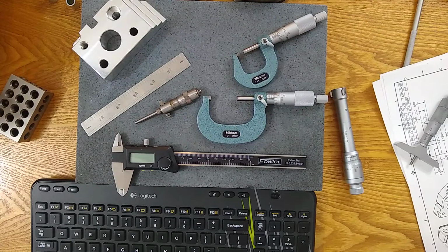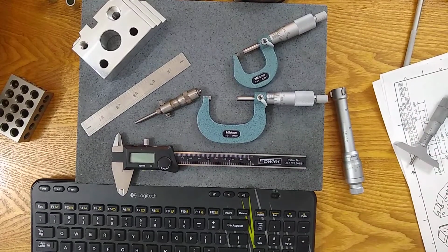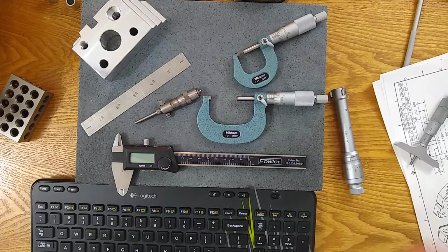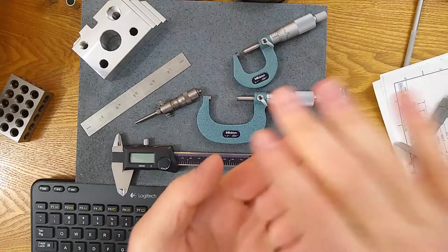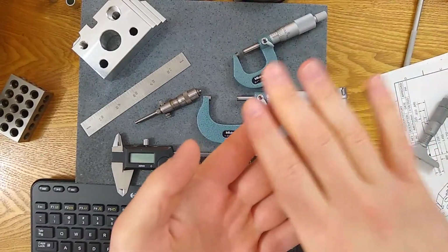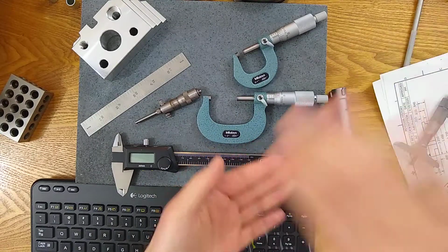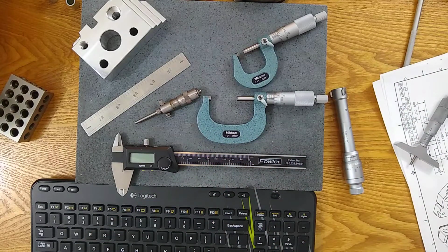There's a very complicated formula that these numbers come out of. I don't feel like it's necessary to share the formula with you, but the CMM manufacturer will tell you the formula so that you can calculate it yourself, but it is quite complicated. It takes temperature into effect, it takes all of your hardware into effect, and it takes the length of the measurement you're doing. As I mentioned, with a height gauge, you might be getting 12 inches or 18 inches of stroke, and with a CMM, you may be even getting larger than that.